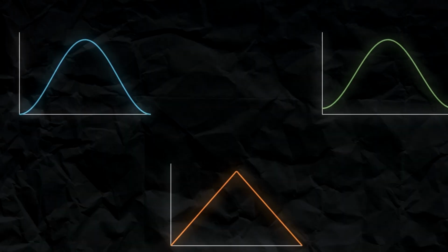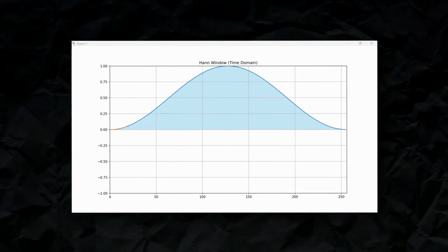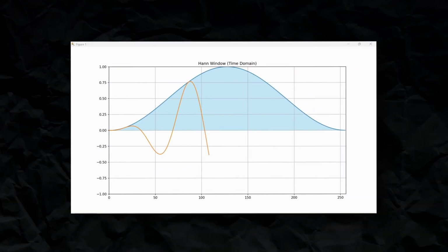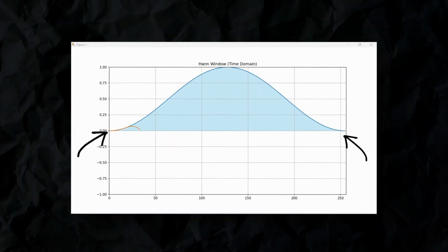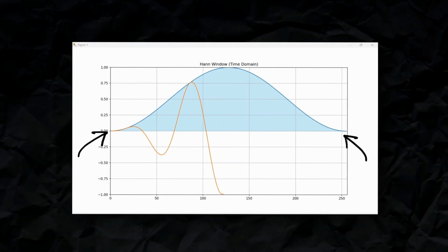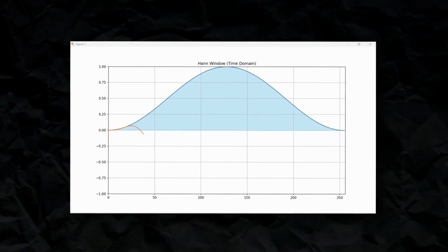So all we really have to do is try to make it periodic, and we can do that by applying another window. There are a bunch of different ones for different purposes, but one of the most famous and generally used is the Hanning window, which has a bell-shaped curve that tapers the ends of our audio, which means that we start and end at 0, almost like it's periodic. This doesn't eliminate leakage entirely, but the amount of help it does outweighs what it can't.